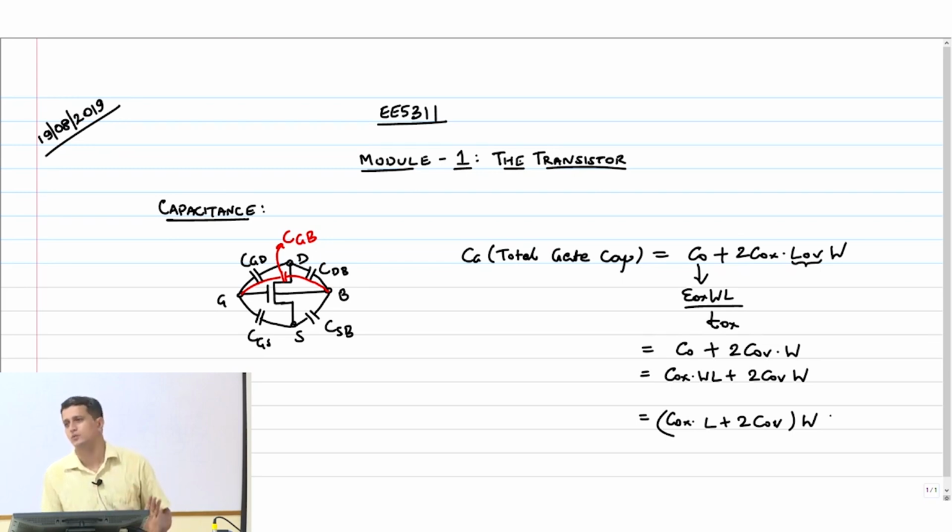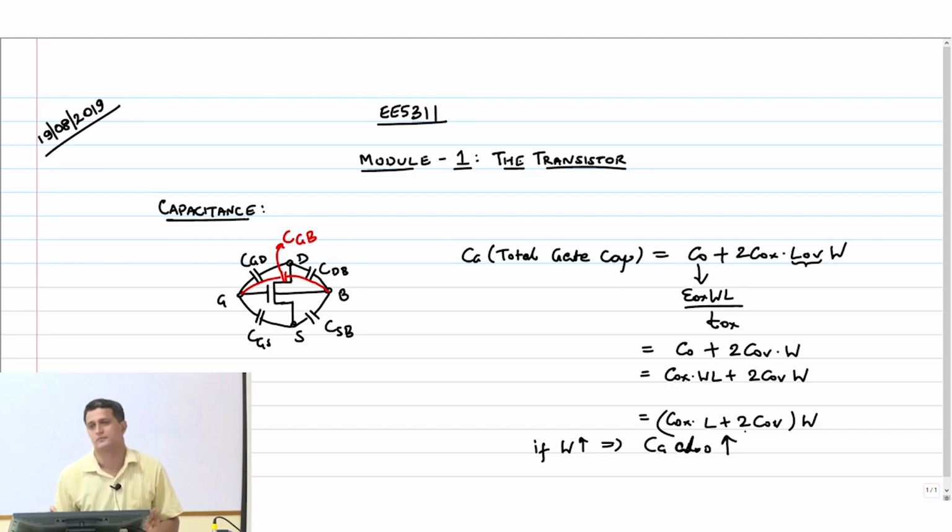capacitances scale with W. That is the main conclusion that we will come to, right. If W increases implies CG also increases. As a designer, this is what you should really know,